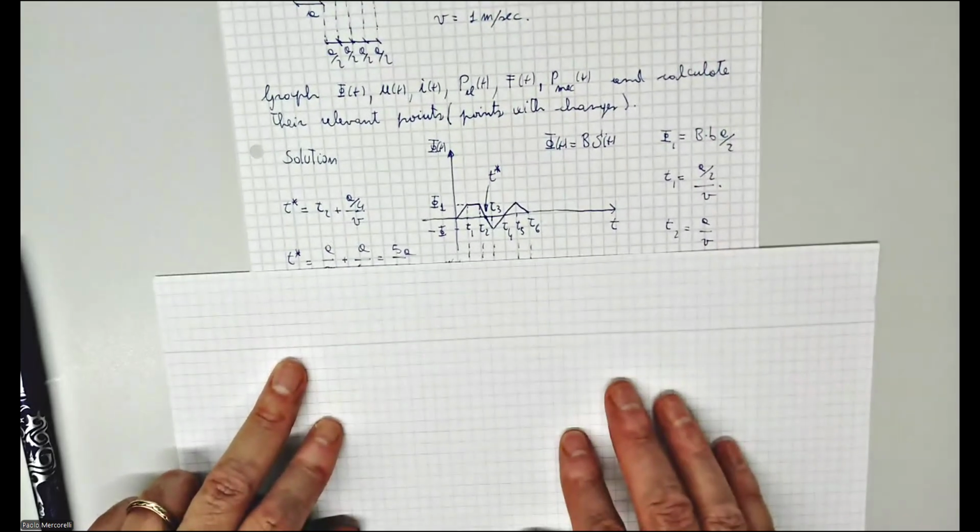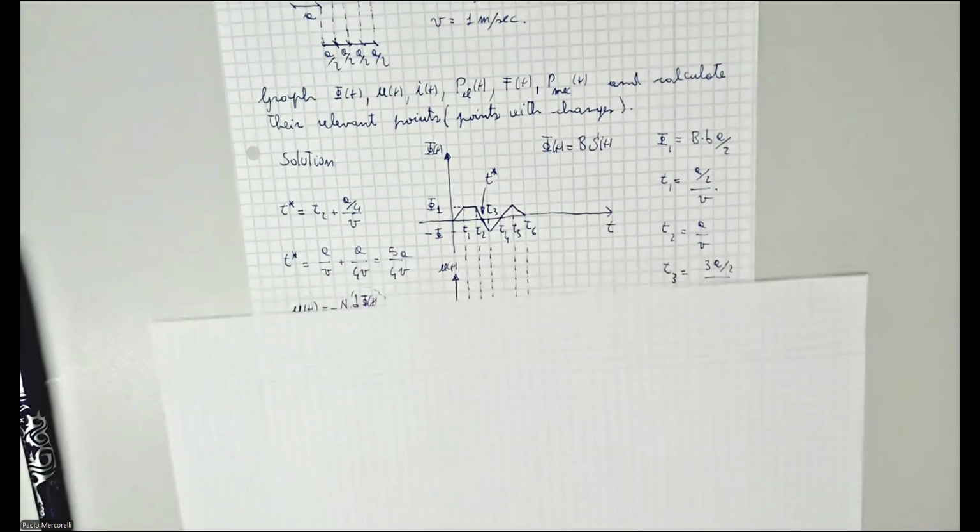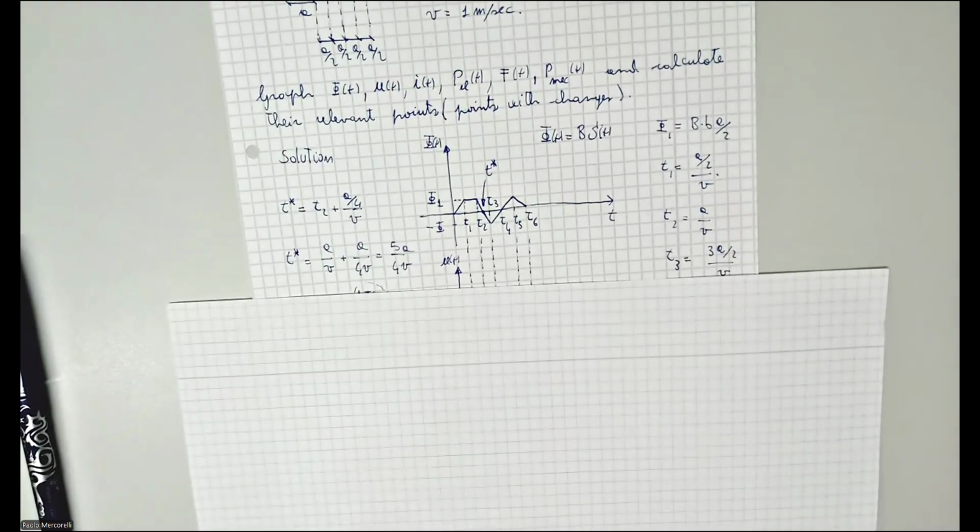Look at the first graph, the phi. It's a little bit small, but we can see. Now, in the data sheet, phi equals B multiplied by S of t. S is the active magnetic surface, or the effective magnetic surface, or the effective surface. If you don't remember, you can look at the datasheet, but try to remember. So it's changing directly over time.